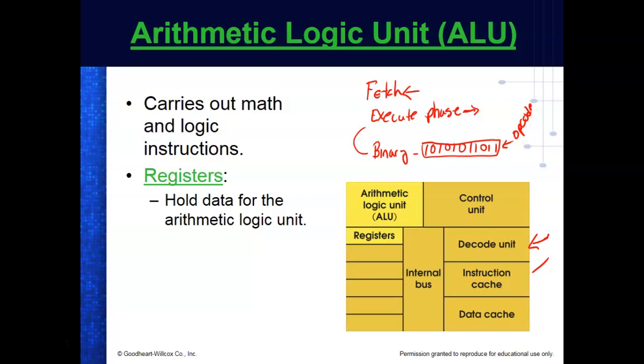And now we have some processors that have like 3 levels of cache in there, level 1, level 2, level 3. Prefetching: level 3 feeds level 2, and level 2 feeds level 1, and these processors scream. These are the 2-3 gigahertz processors out there. Y'all know what gigahertz is, right? Cycles per second. So digital waveforms use a lot of the same terms, but it's not a sine wave, it's just pulses.